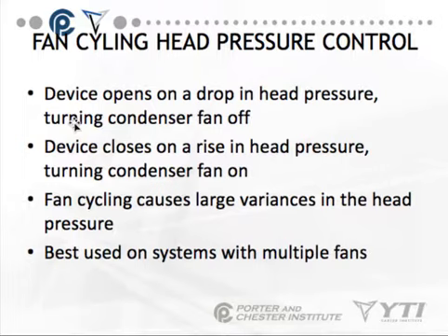The fan cycling will cause large variances in the head pressures, and they're best used on systems with multiple fans. That's the fan cycling head pressure control.